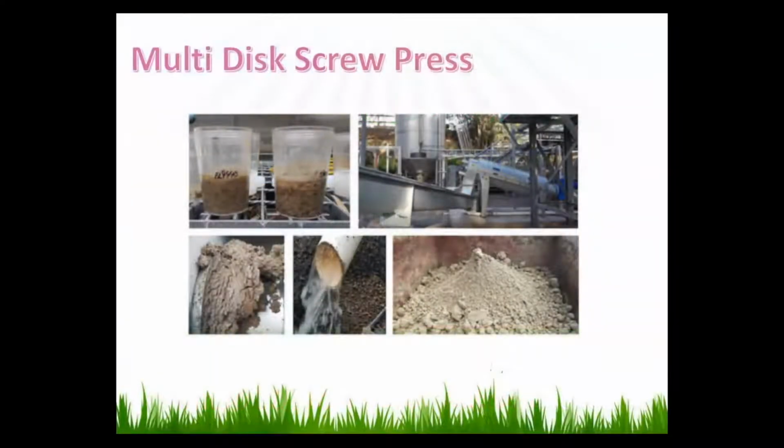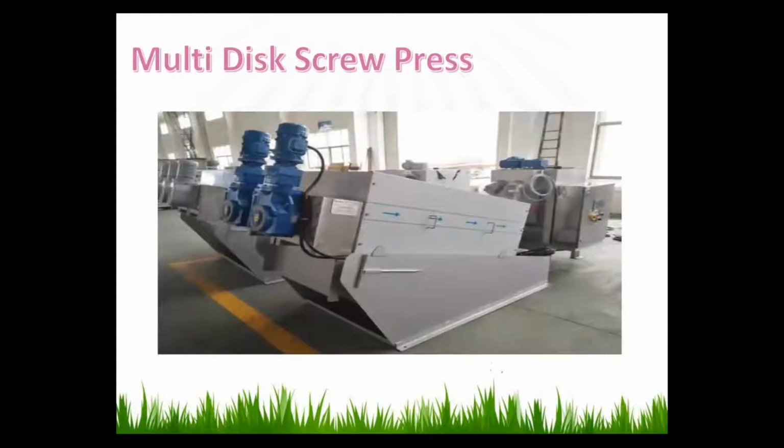Generally, in a wastewater treatment plant, the bulk of sludge is generated from primary treatment, secondary treatment, as well as tertiary treatment processes. The higher the degree of wastewater treatment, the larger the quantity of sludge to be treated and handled. Usually, sludge will be dewatered to remove the moisture content prior to further treatment or disposal. In this method, MDS was designed to replace the conventional dewatering system to treat the higher volume of generated sludge.